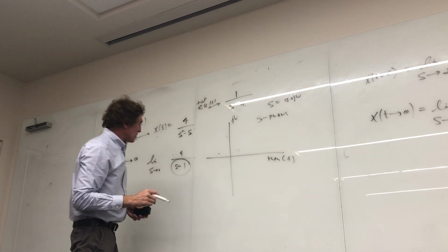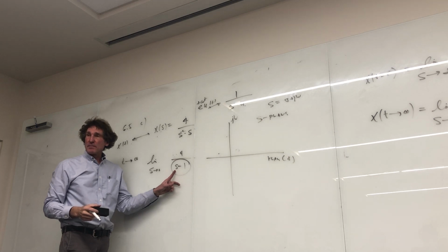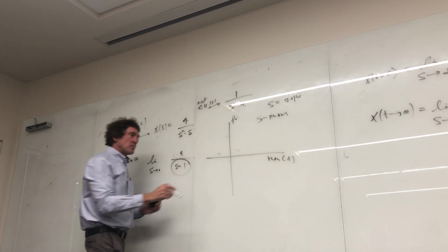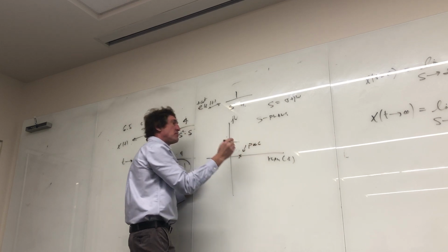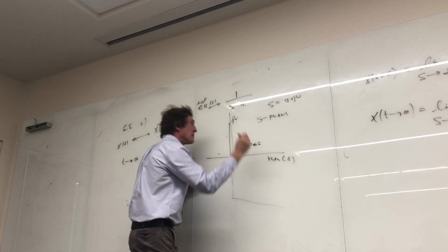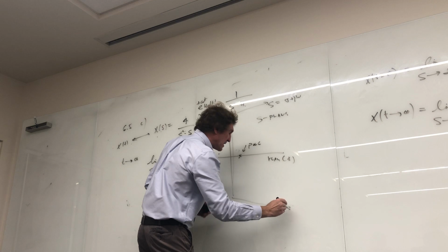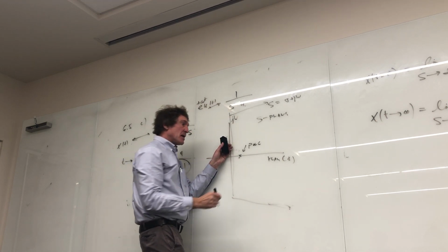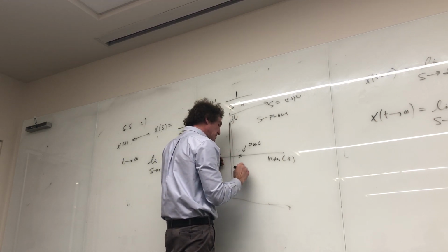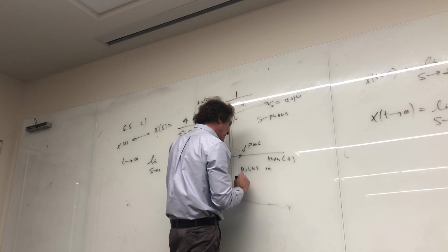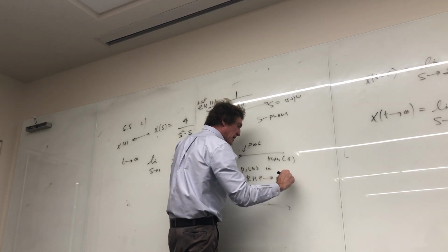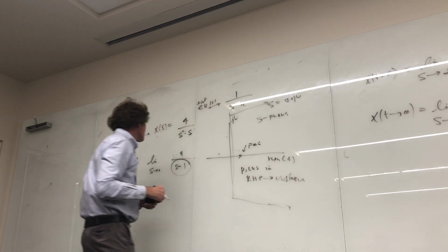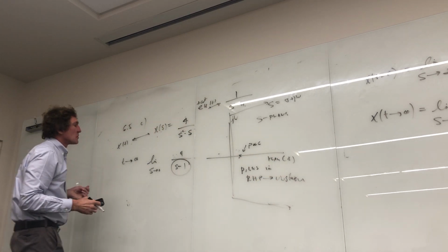When you plot poles, you all see the pole here is at 1. With me? So you put an x there, and that indicates it's a pole. Now any pole in the right half plane, meaning any pole on this side of this drawing, means it's unstable. Poles in the right half plane, unstable. And you don't even have to do this, but technically for this one,